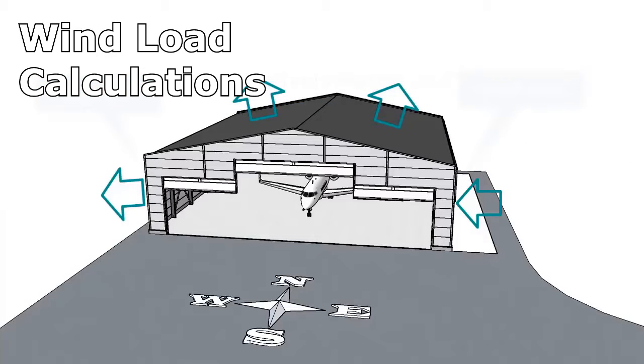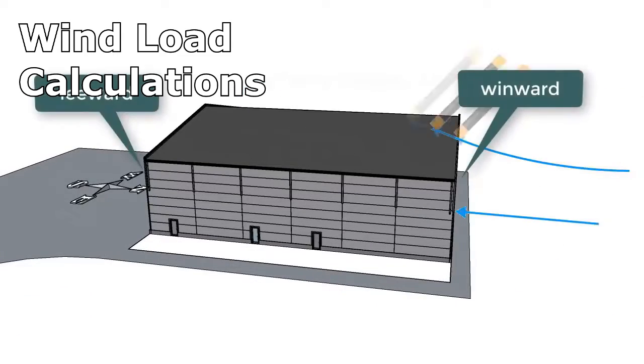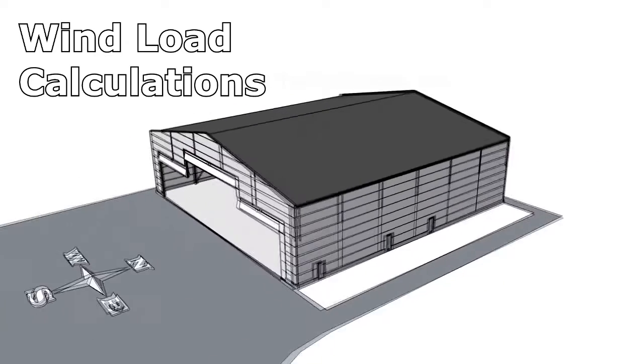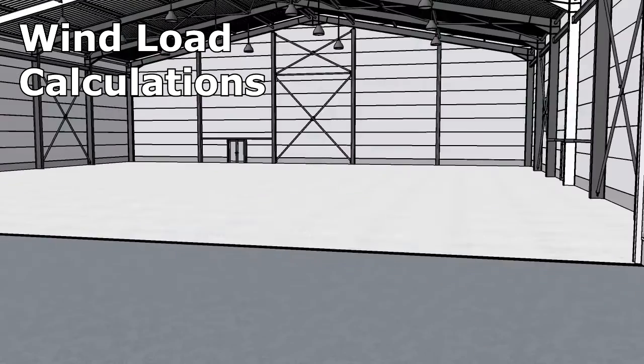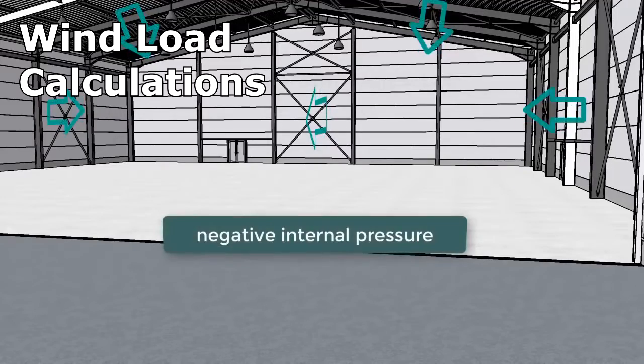The dynamic gust pressure is calculated and multiplied against the net pressure coefficient. These calculations provide the wind pressure. Ultimate wind pressure of purlins was 2.23 kilopascals, while ultimate wind pressure of girts is 0.87 and negative 0.75 kilopascals.